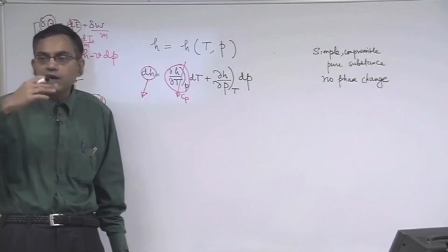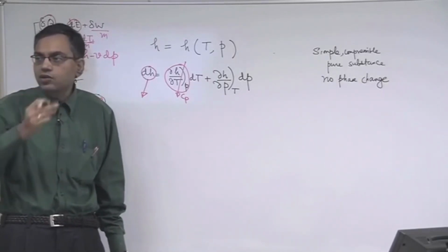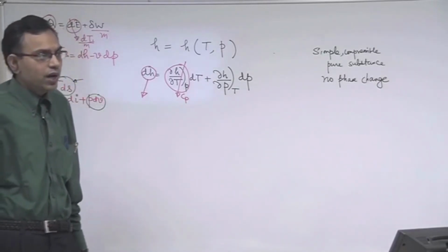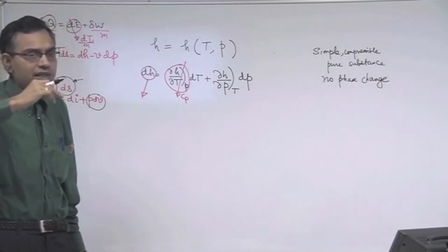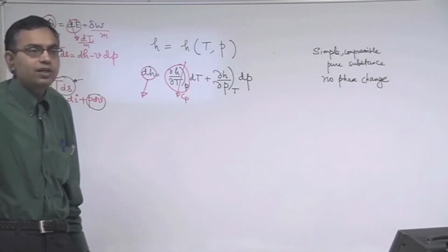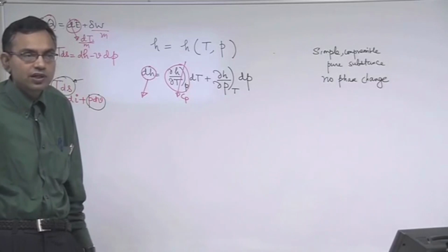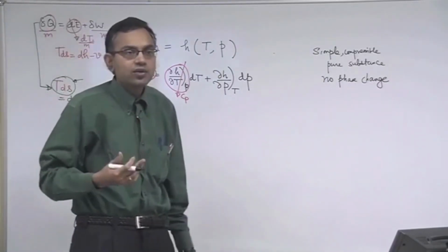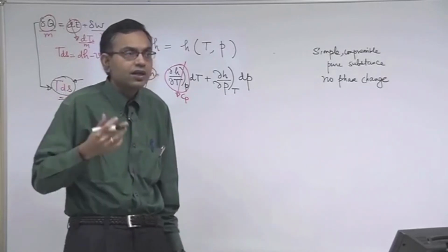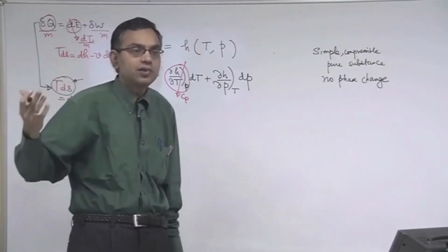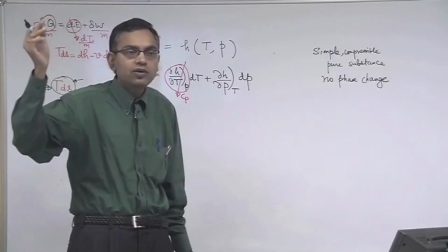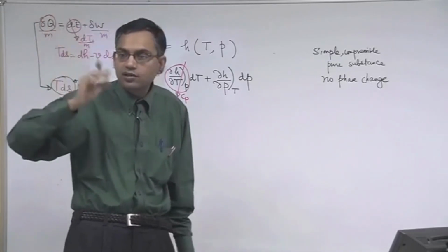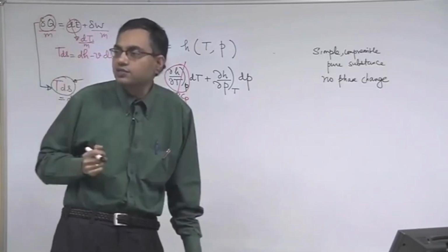To find out the work done as the system undergoes a change of state from state 1 to state 2, you basically have to know the thermodynamic path by which the system has gone from state 1 to state 2. Similarly, you need to do that to find out the heat transfer, but to find out the change in volume as the system goes from state 1 to state 2, only the final volume and initial volume are important, and not how the system has changed its volume.